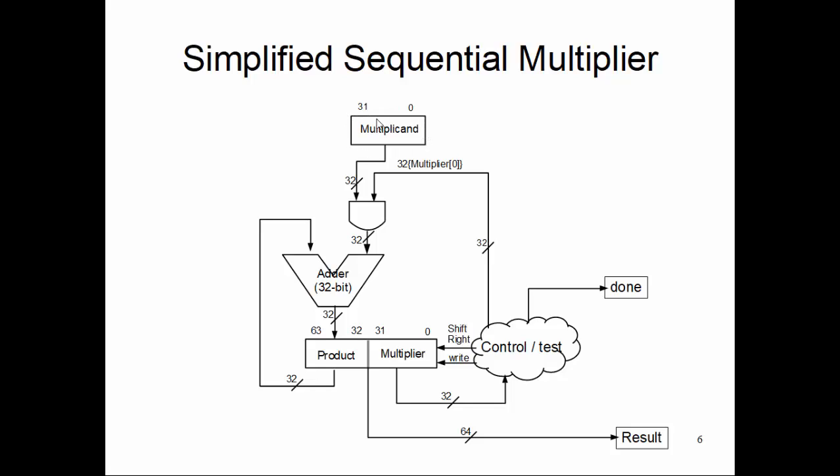We stored the multiplicand in 32 bits, and we stored the product as 32 bits and the multiplier in another 32-bit lower half, and they're connected as I explained: the product LSB will come over to the MSB of the multiplier side, bit by bit. So as the multiplier goes out of scope, it will be replaced by the finalized bit of the product bit pattern. And we deploy an adder of 32 bits. We no longer need a 64-bit addition.